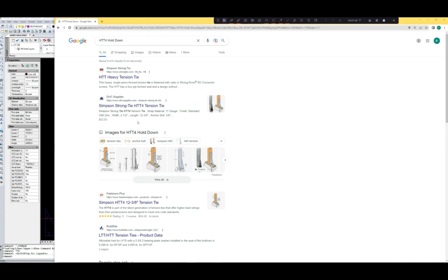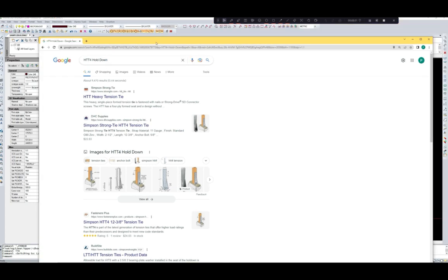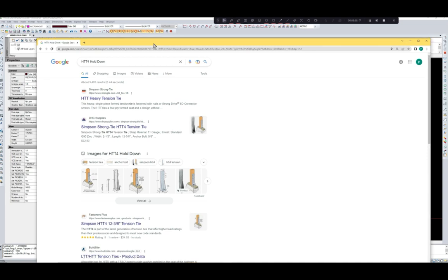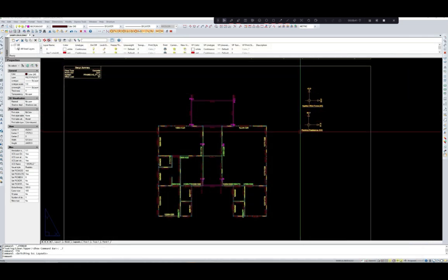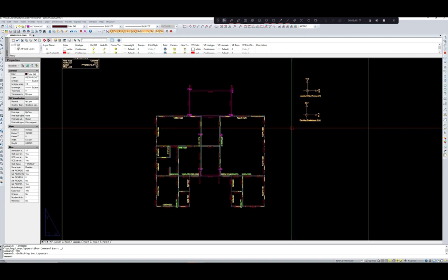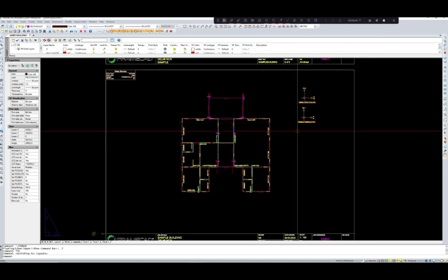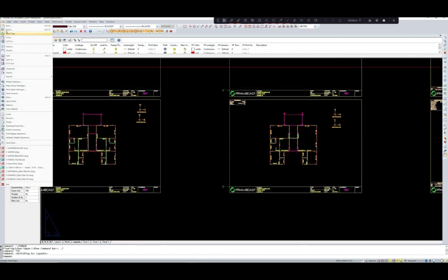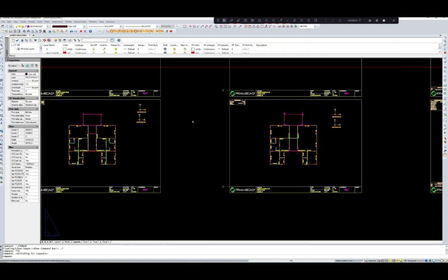After that, you should be able to model, and the next step after completing the modeling is to export this file for the CNC machine. If you practice this much only, you will be able to model and design LGFS structures in FrameCAD. And so now let us save our model. File, go to save, and then exit.